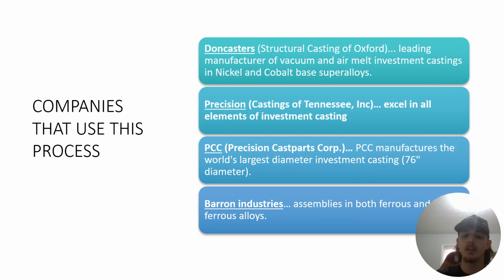So during that video, you saw all 7 of the steps I described earlier in the investment casting process. I wanted to point out a major fact: they used the shell making process 10 times. That's how thick they wanted their shell when they used their molten metal. They didn't want it cracking or anything else like that. And they recycle all of their wax. That is pretty unique, if you ask me.